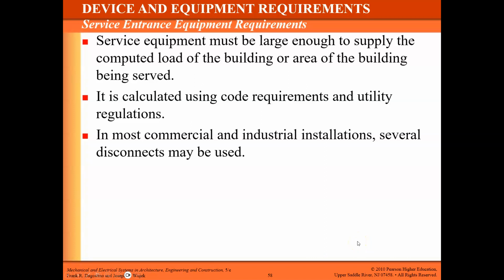So the total amount of service equipment, the capacity of the service equipment, and the amount of electricity brought into a building is going to be based on code requirements and calculations that the electrical engineer came up with, based on all of the equipment, all of the expected things we're going to be plugging in, the various draws we're going to have regularly or intermittently. All of that needs to go into a big calculation and sum it all up so that at any given time, that panel is going to be able to supply all of the required electricity.